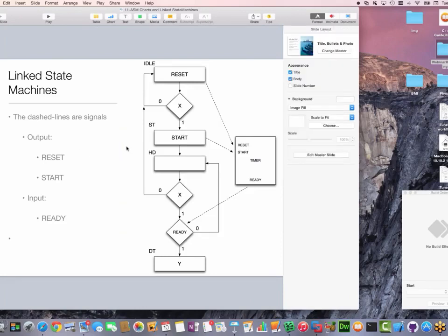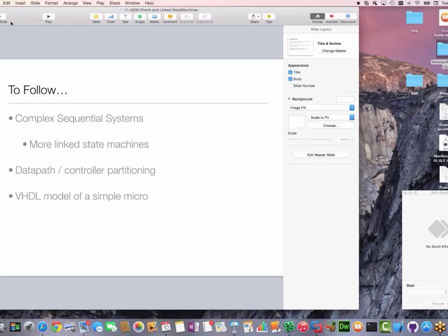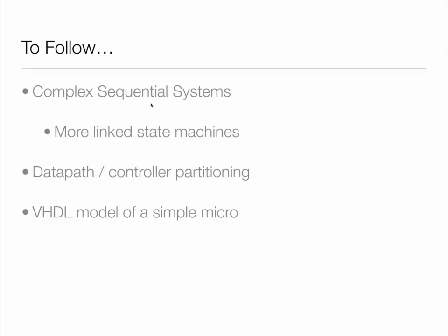I said to quite a few people today, actually, when you build your components, you should really put on asynchronous reset so that when you power on, everything is put into a safe state. That means there's 0 volts on the H bridges so the motors don't suddenly leap into life. So you don't have, on power on, robots jumping off the desk.